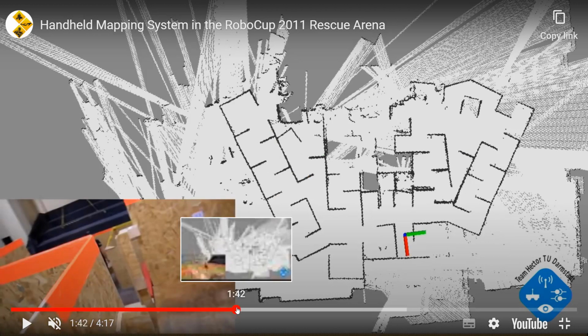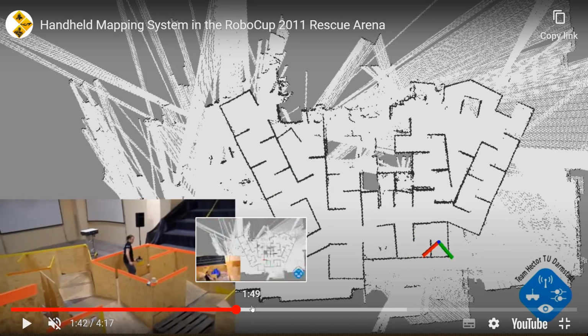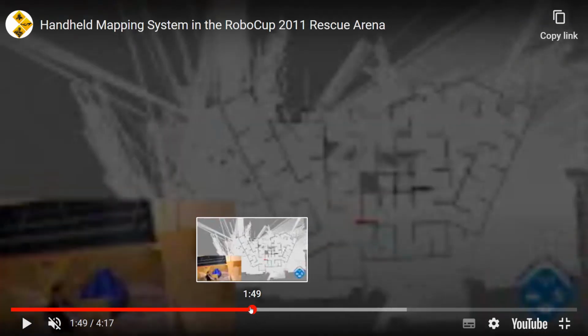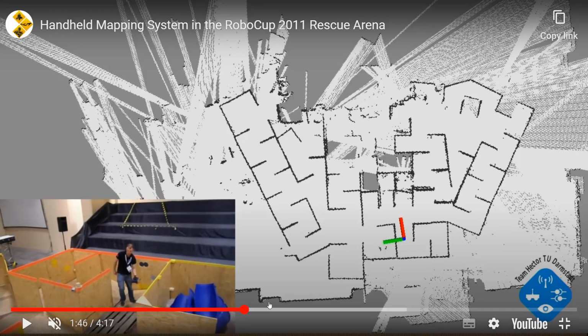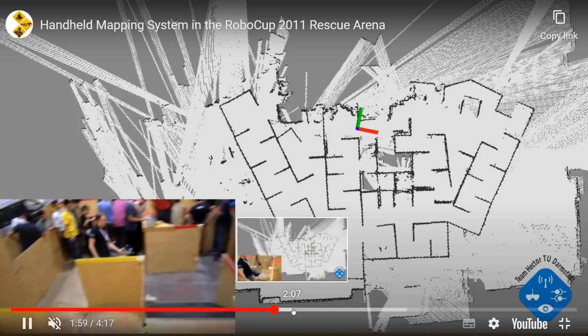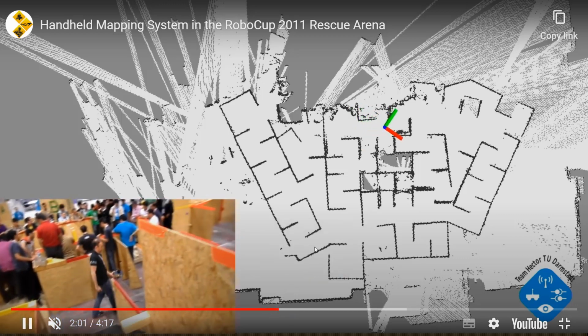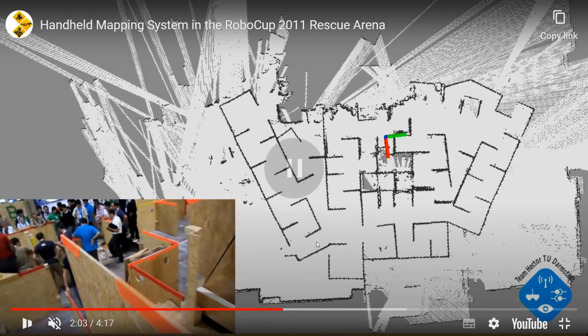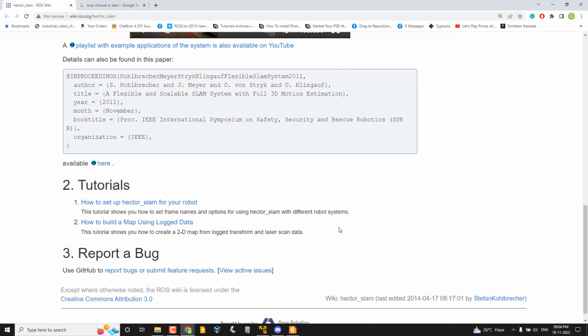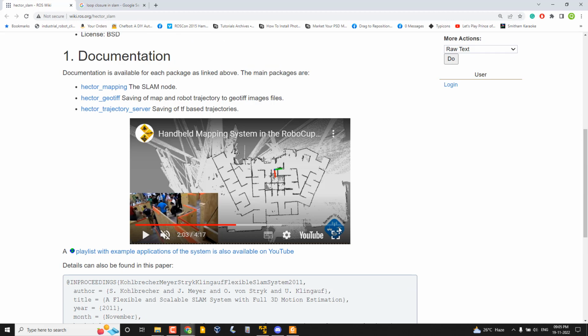So the map is closing. If we consider the map and the reality, both are the same. I think that is the loop closure. Hector SLAM does that without any odometry, using only the laser scan. That is one advantage I have seen with Hector SLAM.